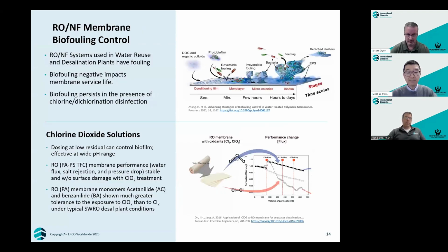Chlorine dioxide can be applied in preventing biofouling of membranes that are used in reverse osmosis and nanofiltration systems. These treatments are increasingly being used in saltwater desalination, brine treatment, and reclaimed wastewater treatment for potable and non-potable reuse purposes. Microorganisms are very good at developing biofilms at the surface of membranes and feed spacers.